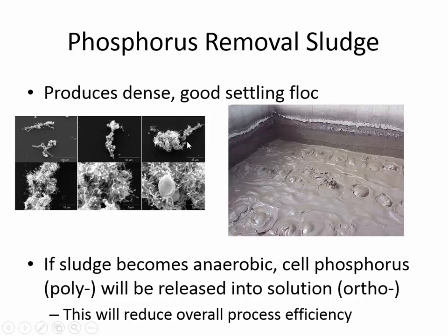And so look at, here's some nice bubbling sludge. They've got these aerators in here. You really have to aerate phosphorus-containing sludge a lot, because if you don't, then all that work you went through of concentrating the phosphorus will backfire, and it's just going to release all of that stored phosphorus into ortho.